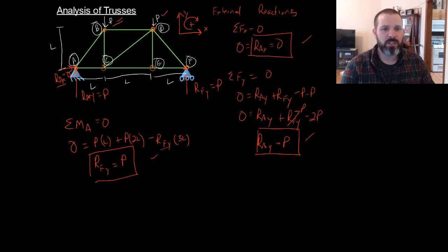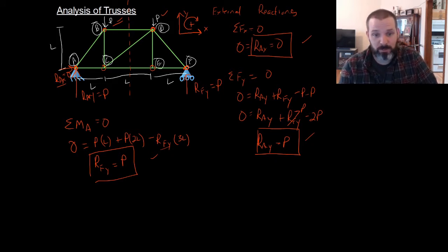It's called symmetry. If we look right down the middle of the truss, we see that we have both our reactions spaced an equal amount apart, and the truss is symmetric across this line. And we have two loads spaced an equal distance apart. When you have a symmetric structure, you can always just add up the total loads and divide them by 2.